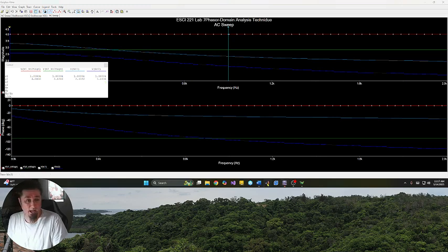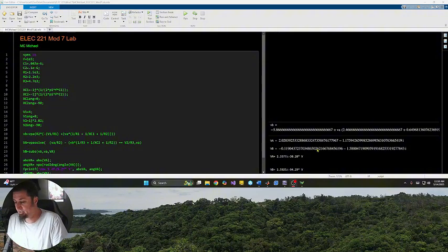Finally, if we go into our MATLAB and connect this to our calculations, finally comparing this to our MATLAB, we had VA of 2.3377 and a phase angle of negative 30.20 degrees. And VB we had at 1.5925 magnitude and an angle of negative 94.29 degrees.